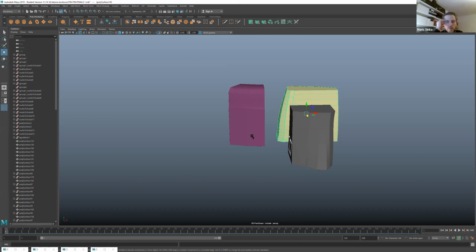But then maybe steel pipes put in while printing, just a cut pipe, and then you have a hole. Yes, but if the pipe is quite large, it will influence the print, and the material will leak out a little bit. But of course, it is the place where you join the elements together, so it's not possible to see, and we can smoothen it out once it's printed. So maybe it's not a problem.